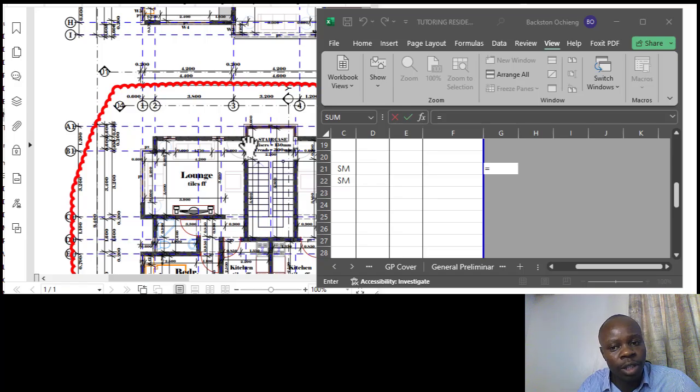So we move on. The safest way in which you can always compare whether your drawings are in order, or the sections you're checking are the correct ones, is by the use of grids. So the exact part that we need is just slightly beyond grid B1 towards A1. Alright, and that is the part where we have that particular column. So when you look at it, it's the area for the staircase.